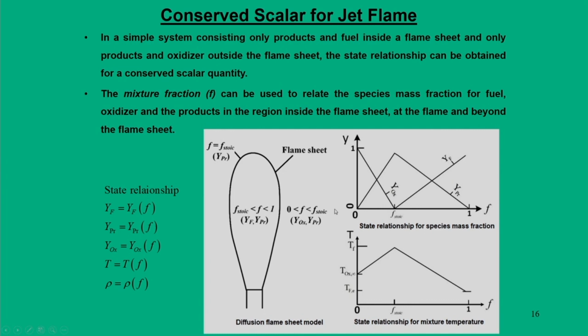Based on that, if you look at a flame sheet, we can have 3 distinct locations. One is on the flame surface, where F is equal to the stoichiometric value. At that point, almost exactly the entire combustion has happened, and Y products is equal to 1.